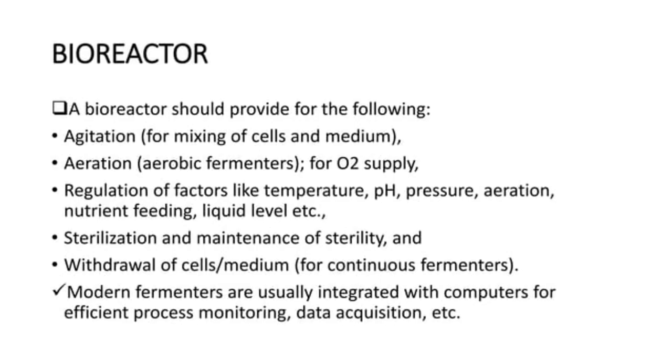A bioreactor should provide the following: agitation, aeration, regulation of factors like temperature, pH, pressure, nutrient feeding, liquid level, etc., sterilization and maintenance of sterility, and withdrawal of cells and medium. Modern fermenters are usually integrated with computers for efficient process monitoring, data acquisition, etc.